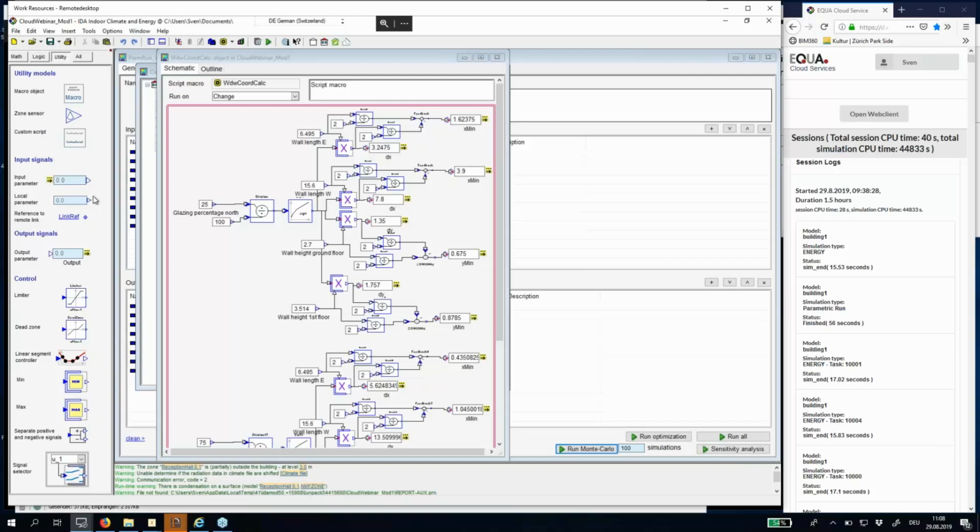I might add there that a tool like GenOpt is actually not benefiting very well from the cloud at all, because it uses parallelization to a relatively limited extent, and then it goes into sequential mode and tries to find the precise optimum in this sequential mode. And this last part is seldom interesting actually for building simulations.